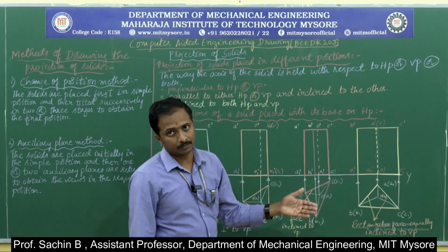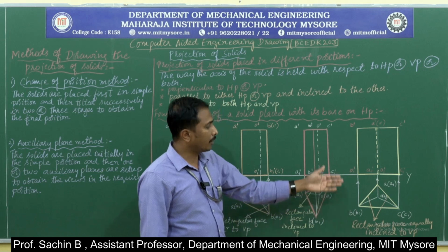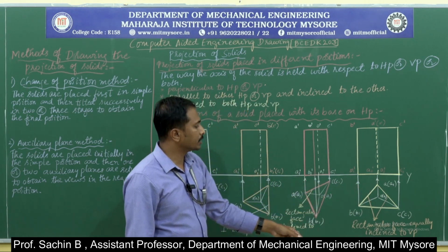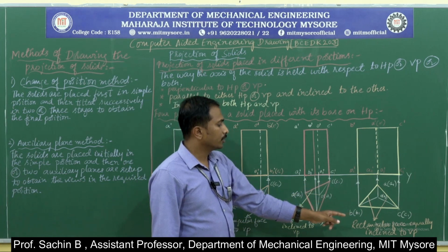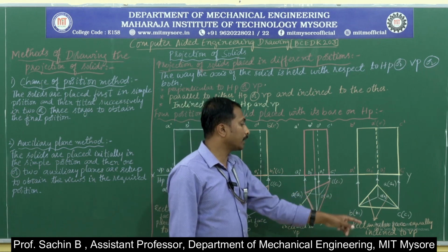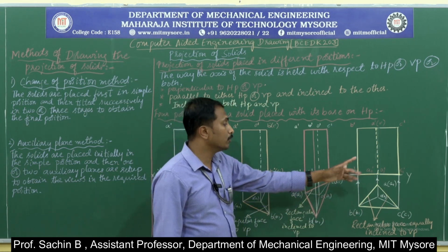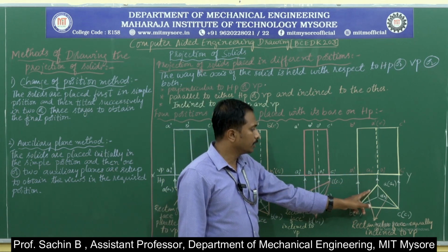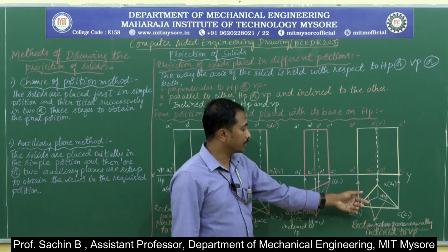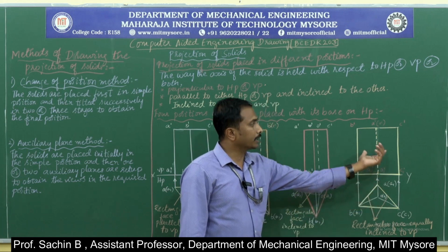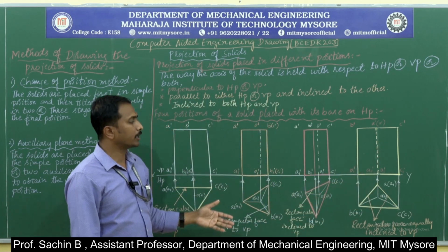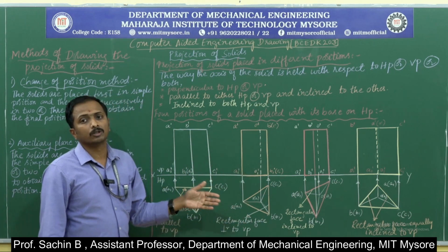the axis. Apex near to the axis or apex away from the axis. Just observe here, in this particular condition, the triangular prism will be resting on HP, but the rectangular faces are equally inclined to VP. Means you just observe here, the rectangular faces are equally inclined to VP. That is the condition. Again I have written the top view, and again I have written the front view of the object. These are the 4 possible conditions to solve many of the solid problems.